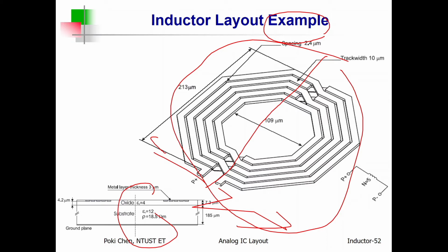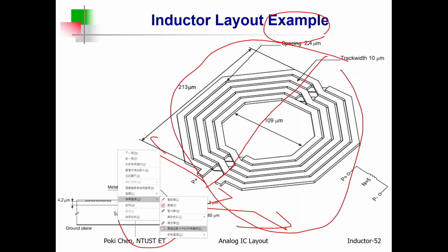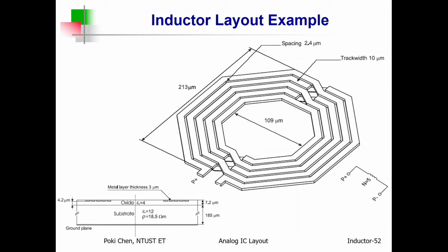Okay, and this is some kind of simulation. They did such kind of simulation through ASITIC. They composed the free program ASITIC. They simulate all those inductors with ASITIC. But if you would like to simulate it with the help of ASITIC, you need to know the thickness of your substrate, the epsilon of your substrate, everything. Okay? Yeah, anyhow, you need to make it by yourself.